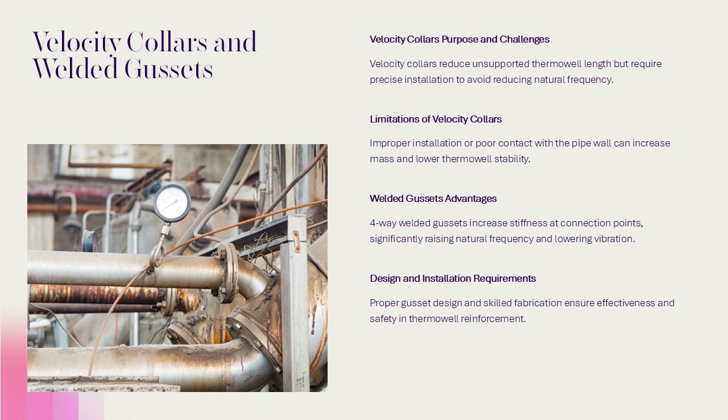Structural reinforcement can enhance thermowell stability, but its application requires caution. Velocity collars aim to reduce the unsupported length of the thermowell, theoretically increasing its natural frequency. However, achieving sufficient contact between the collar and the pipe wall is difficult, and improper installation may reduce the natural frequency due to added mass. Therefore, velocity collars should not be the primary corrective measure.